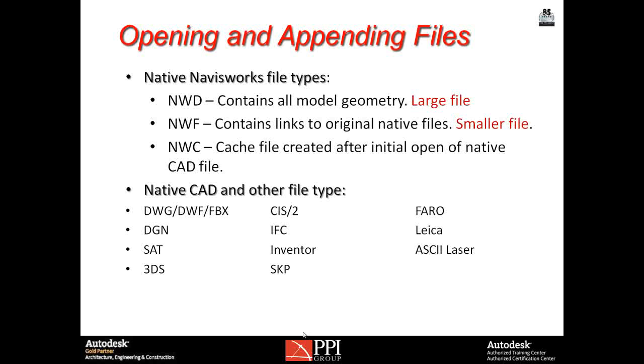A file can be saved in NWC or NWD format using the exporter. A number of readers exist where certain native file formats can be read directly into Navisworks. These are the preferred methods by which to view files in Navisworks. Navisworks also supports a number of additional file readers for applications without a native file reader or exporter. These applications can also usually export to or save as one of the file formats.